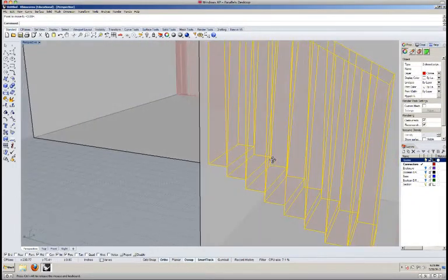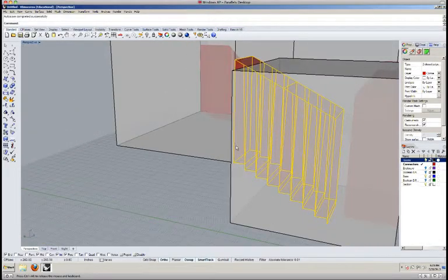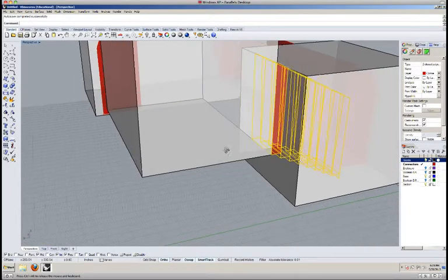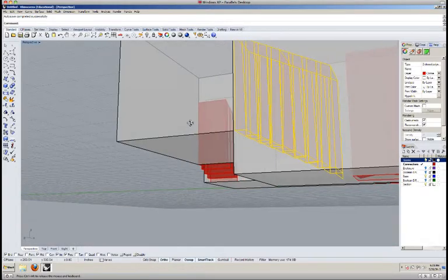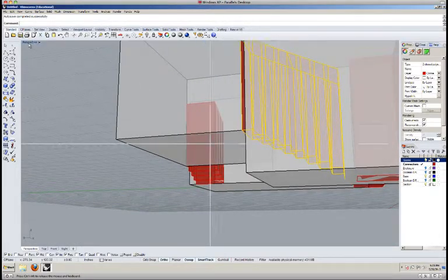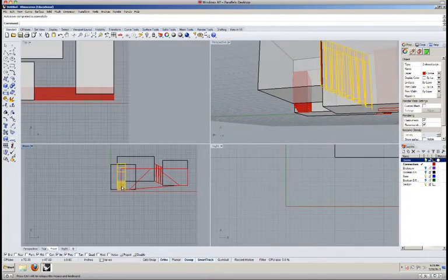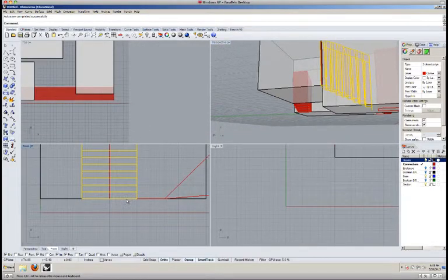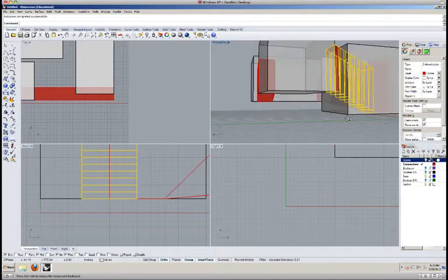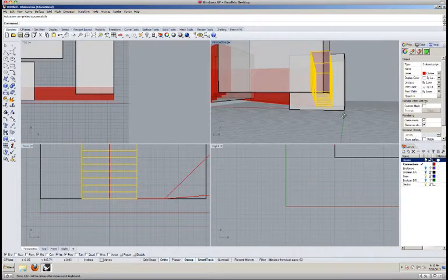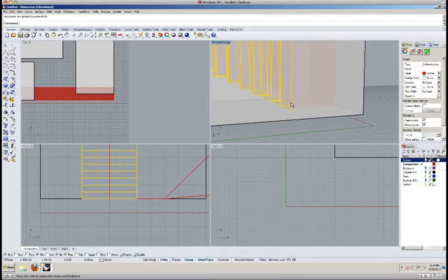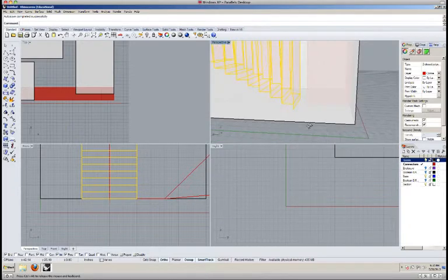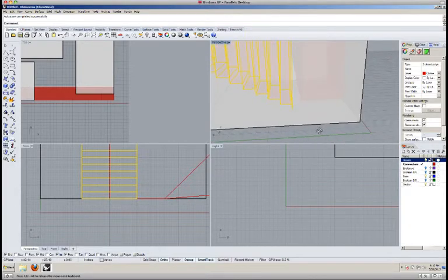So now they should be starting at the same height as the previous volume and connecting down into the base of the other. I can double check that in one of the side views. So I can double check over here that my last riser, which is the bottom here, is connecting to the bottom plane, and I can eyeball the fact that I've got at least 4 feet.